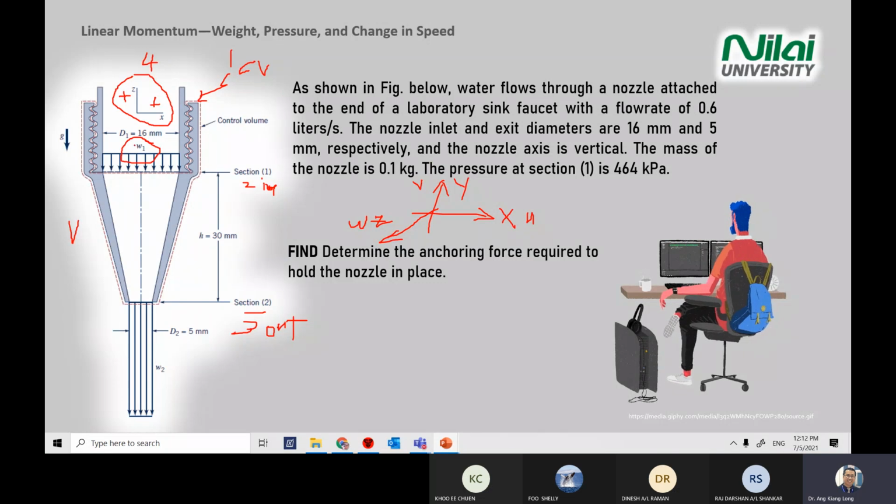Okay, so in this case, why do you use W? Because the axis gives you the Z direction. So be careful. This is an area where students will always forget. When they answer, they will look at this tutorial question and forget that the lecturer did change the axis. Then they will give me the answer according to this tutorial question, and the answer will snowball, they get the wrong answer. So make sure you check your reference axis before you answer.